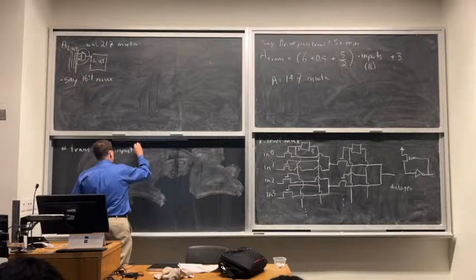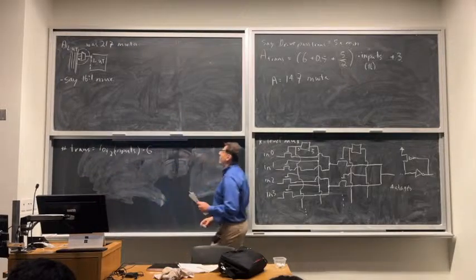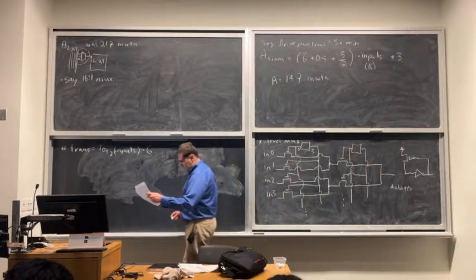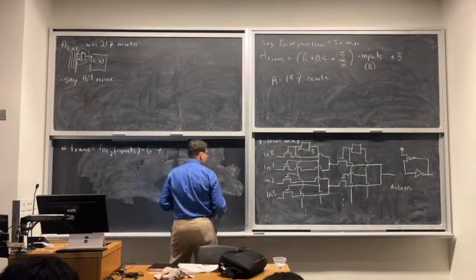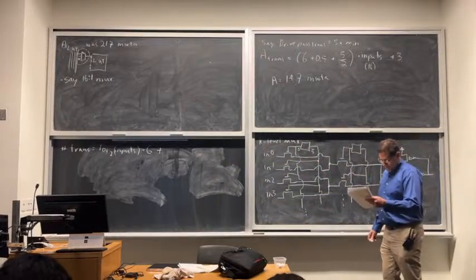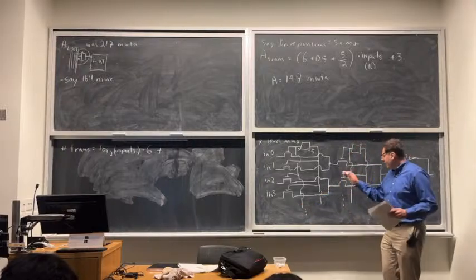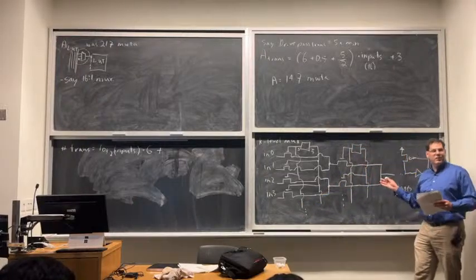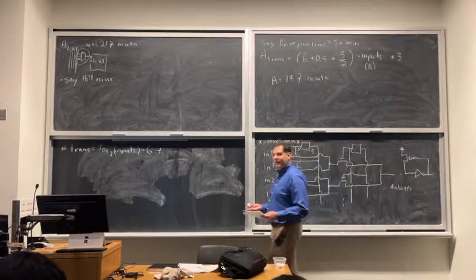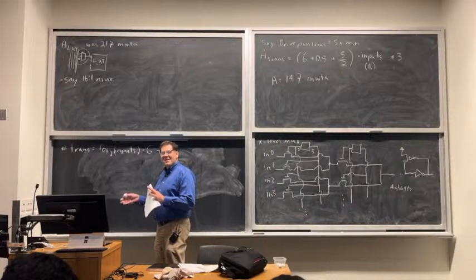Okay, and then I'm going to need, I already showed up somewhere. I guess I've hidden it, but I need 6 transistors per SRAM cell. Okay, and then I need these pass gates. How many pass gates in this whole structure? So the first stage would be 16, or the number of inputs. Second stage would be half that. Third stage would be a quarter of that, and so on. So it's a geometric series. So what's the sum of that geometric series?